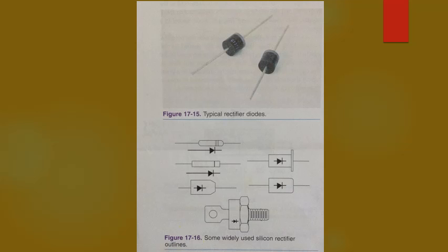Point contact diodes. The point contact diode is used for detection and rectification. It consists of a small piece of N-type germanium crystal. Against this crystal is pressed a fine phosphor bronze wire. While the diode is being made, a high current is run through the diode from wire to crystal. This forms a P-type region around the contact point in the germanium crystal. The point contact diode therefore has both the P and N-type crystals. Its operation is like that of a junction diode.